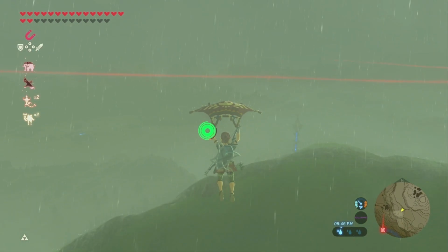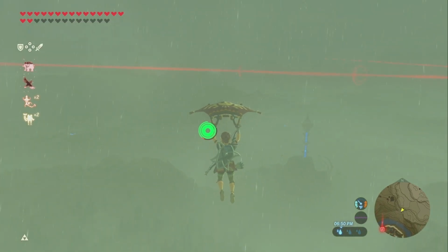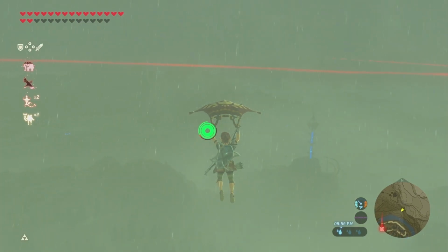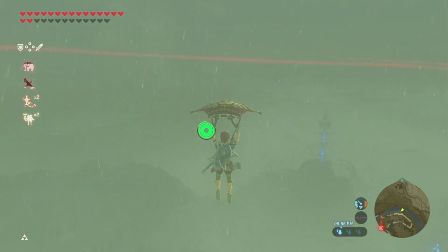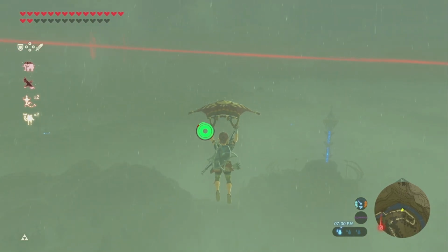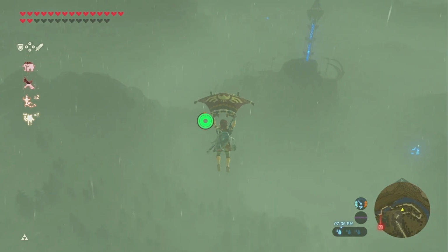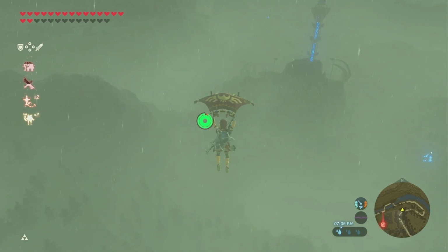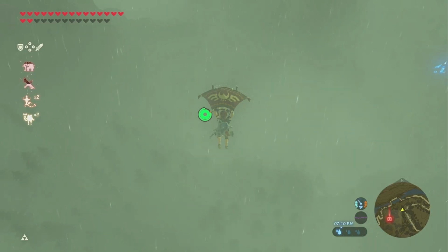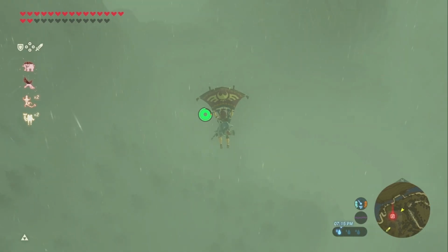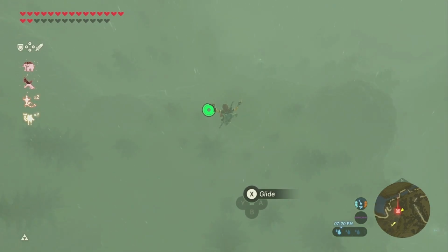Other water heaters: fan-assisted gas water heaters, dual water heaters, circulating water heaters, high-efficiency gas water heaters. Parallel heaters, installed in parallel rather than series. Each heater does the same amount of work. In series, the upstream tank does most of the work. The pipe lengths running to each heater must be of identical length. A lot to read here as well.